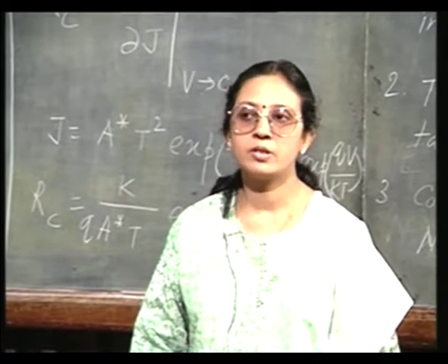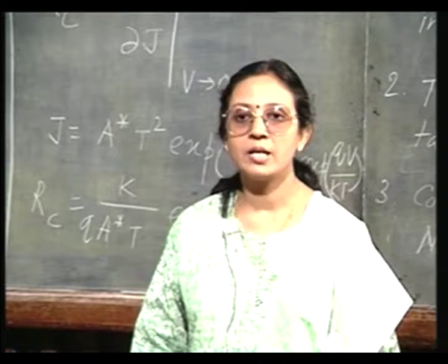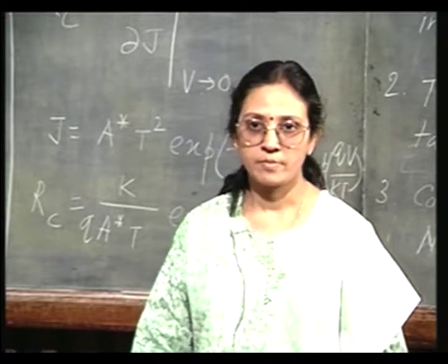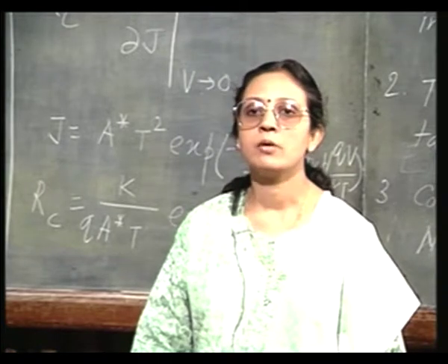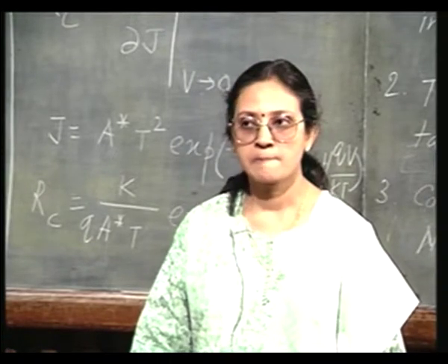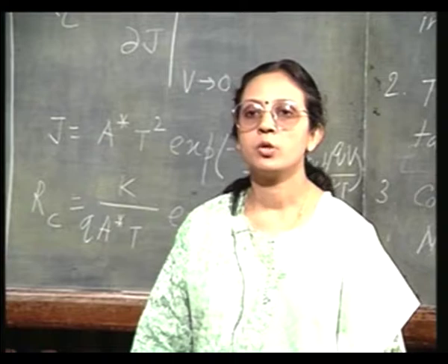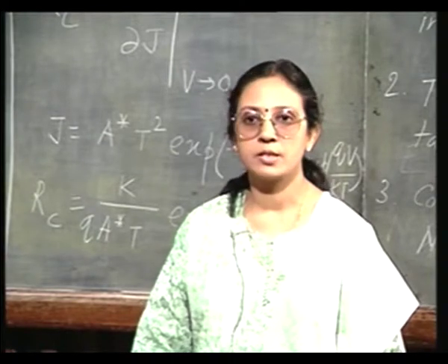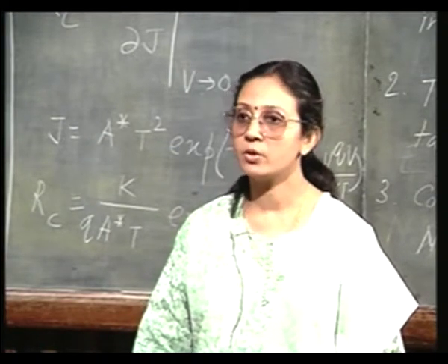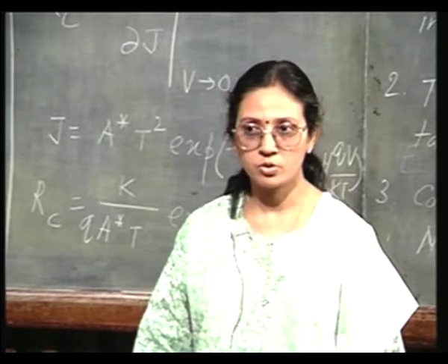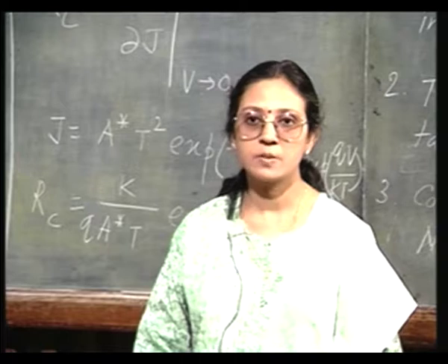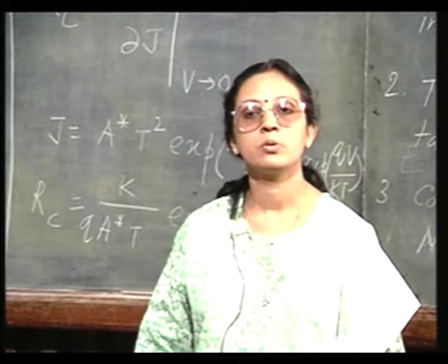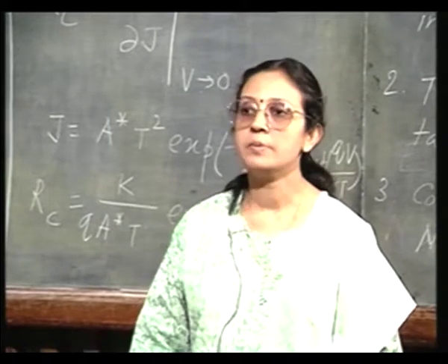Particularly when the material has very high melting point, very high vaporization point, then it is useful to have E-beam system. For example, if you want to evaporate copper, let us say copper or nickel, you see they have very good thermal conductivity also. So, it is very difficult to heat it just by resistive heating. So, then we generally use E-beam technique.